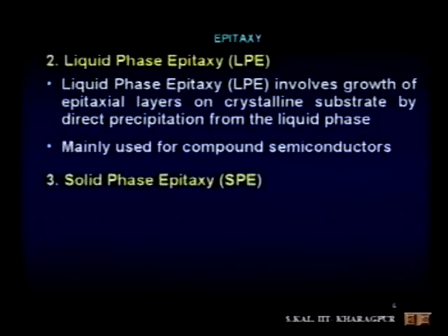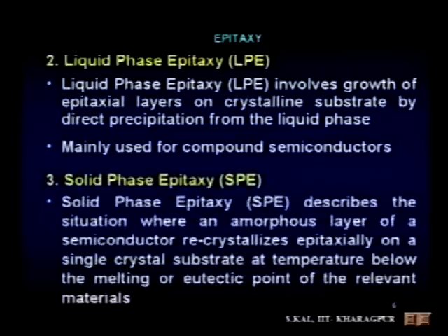And another is SPE, solid phase epitaxy. Solid phase epitaxy describes the situation where an amorphous layer of a semiconductor recrystallizes epitaxially on a single crystal substrate at a temperature below the melting or eutectic point of the relevant materials. That means in SPE, basically the amorphous layer changes into a single crystal layer.